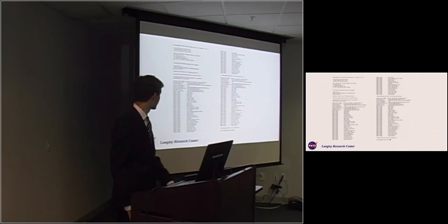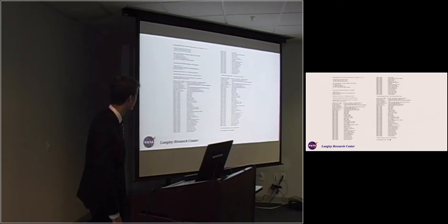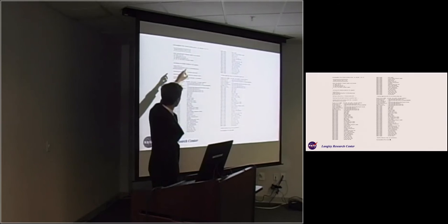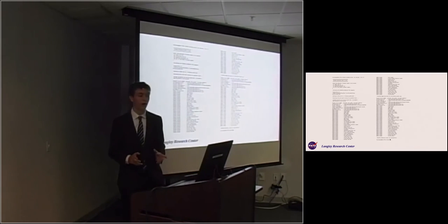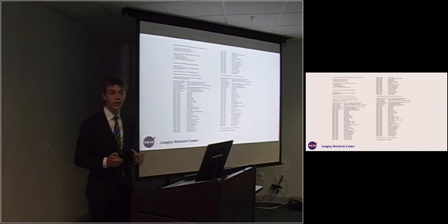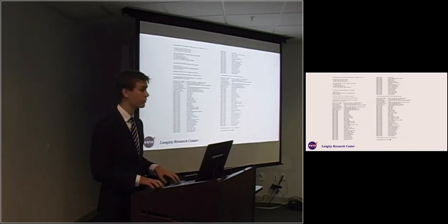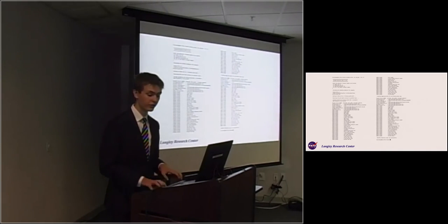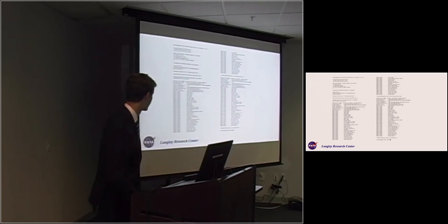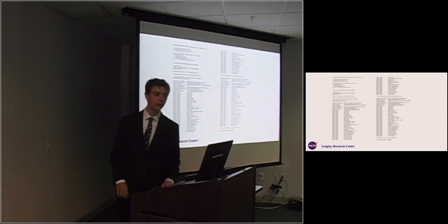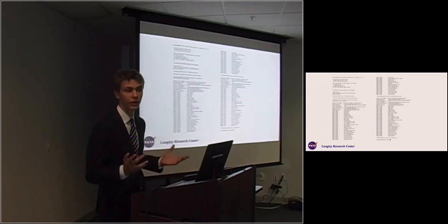Right. So this is a screenshot. It might be a little bit hard to see, but this is a screenshot of our program running. You can see I say validate VULCAN for this case number 5, and then it provides me with a list of transport models that I can use in order to solve for this equation. I chose model number 1, which is the power law. It then runs that case for model number 1 and outputs the data. And you can see it successfully runs. It says VULCAN validation for the turbulent plate .dat succeeded. That is the case that we're running.